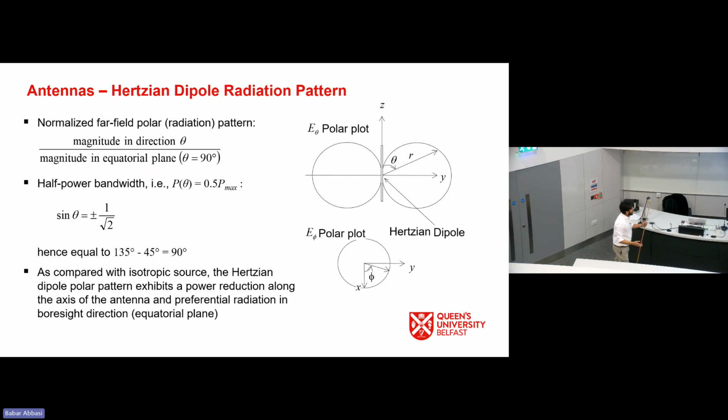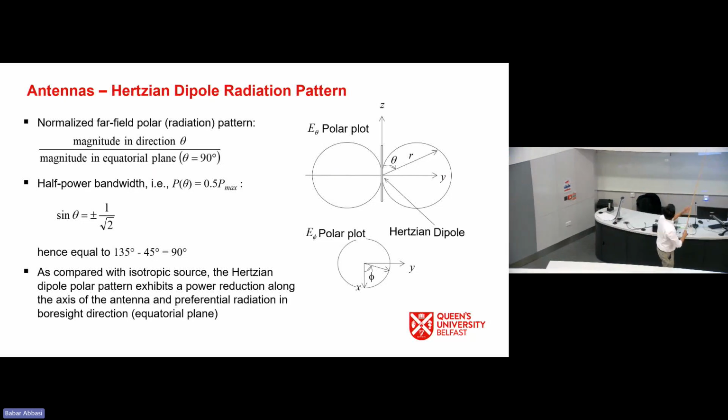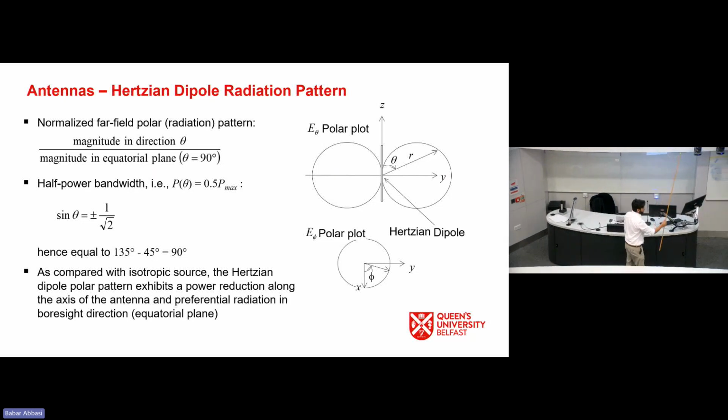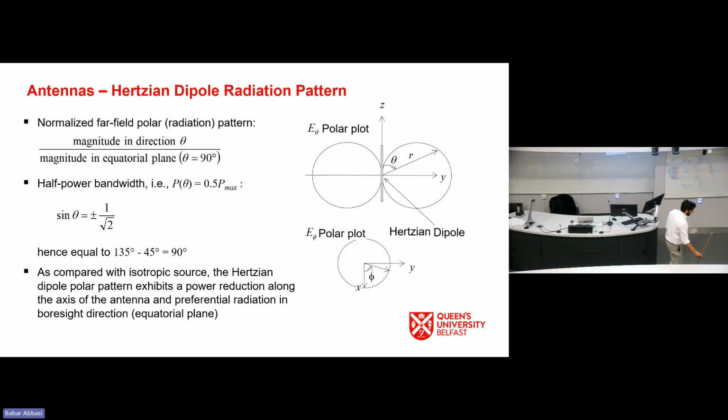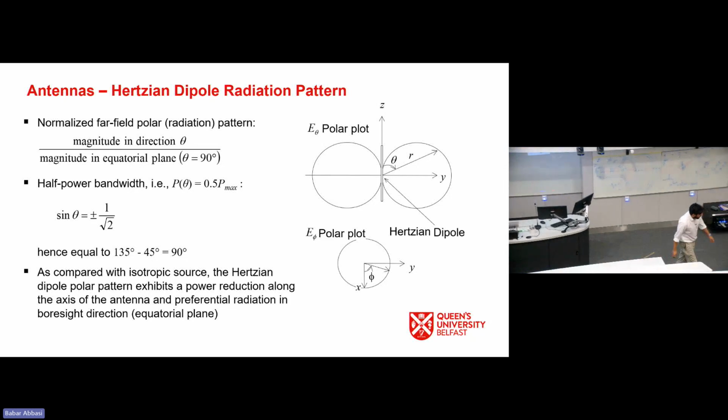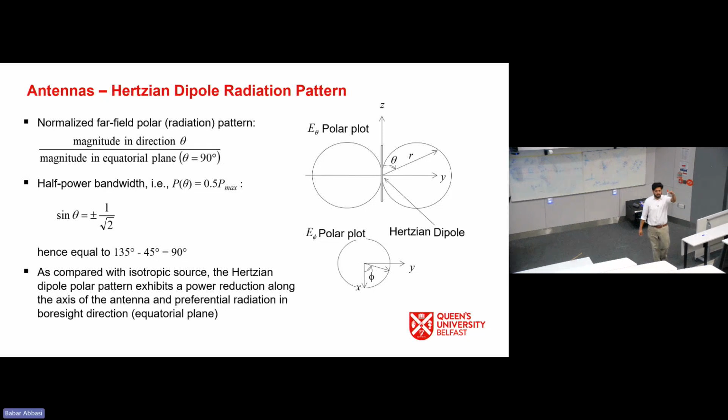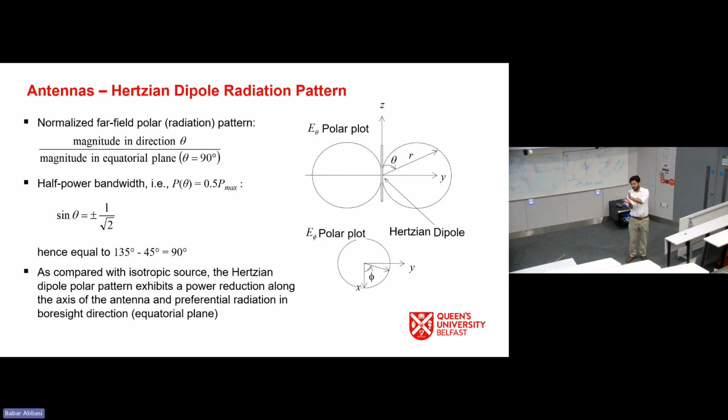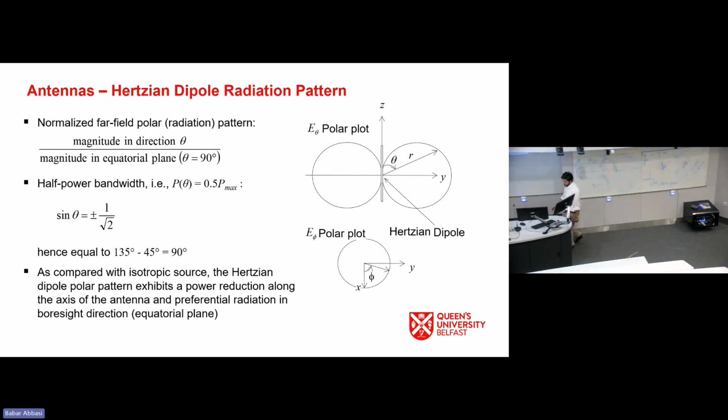For a simple dipole antenna, this half power beamwidth is almost 90 degrees. So what it means is, if I have a dipole antenna here in my hand, like this, then it will radiate over 90 degrees. Its sector will be 90 degrees all around, like this. So half the power will be residing in this 90-degree area, and all other energy will be in other directions. So this is a fictitious definition.